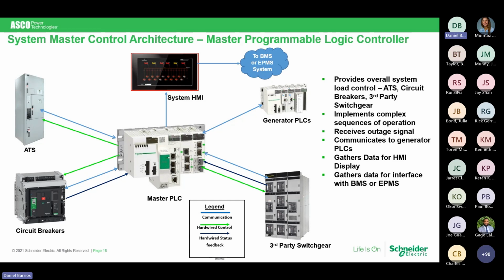When you run Ethernet, Cat5, Cat6 type cable, you are limited to around 328 feet. If you exceed that, now we're speaking fiber. The reason I point that out to you is that it can be something overlooked. It can be overlooked in the plans and specs. It can be seriously overlooked by your installing contractor who tells you, I didn't have any fiber in this.